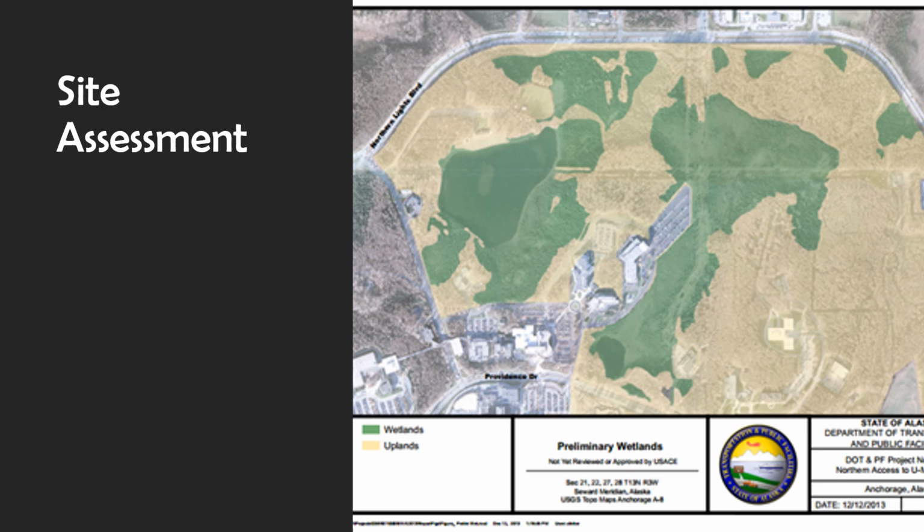The hydrology, looking at flood hazard areas, wetlands, lakes, streams, shorelines, rainwater collection and reuse opportunities, and the capacity of the site to absorb water. Climate, looking at solar exposure, sun angles, and temperatures throughout the year, and at wind, monthly rainfall, or snowfall.